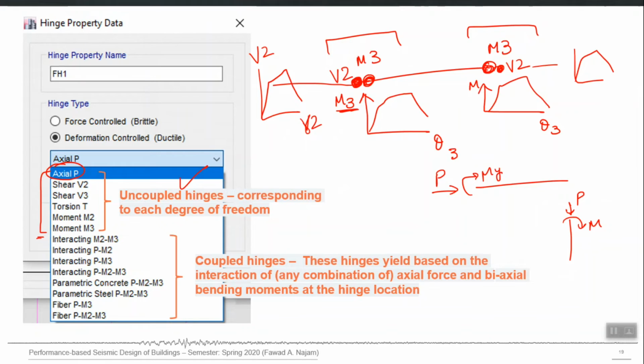So in a beam, the degrees of freedom can be assumed uncoupled because the interaction is not significant, it is negligible. The beam is primarily bending in flexural action only, the axial load is not significant. For columns, both axial load and moment are significant, and they are interacting to cause damage in that particular column. So therefore the capacity of a column cannot be defined only by one number, it is defined by a pair, and there can be infinite different pairs which can fail a particular column.